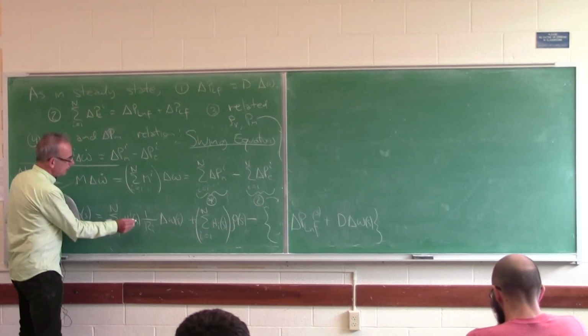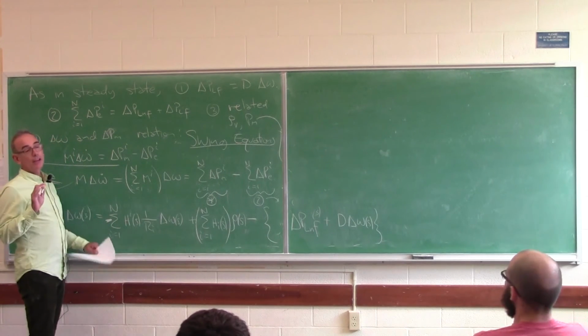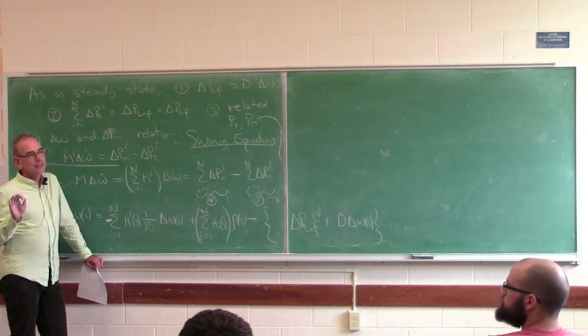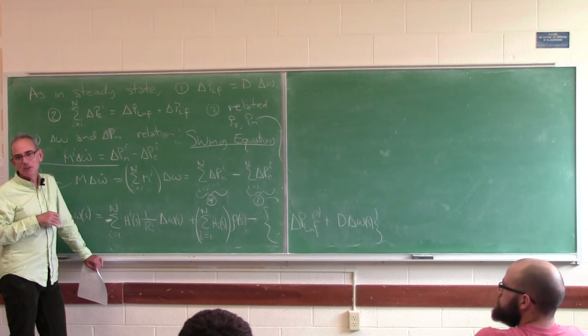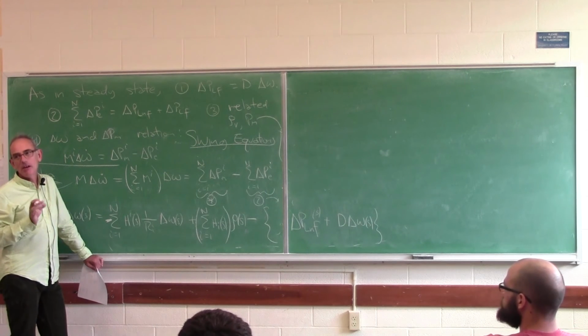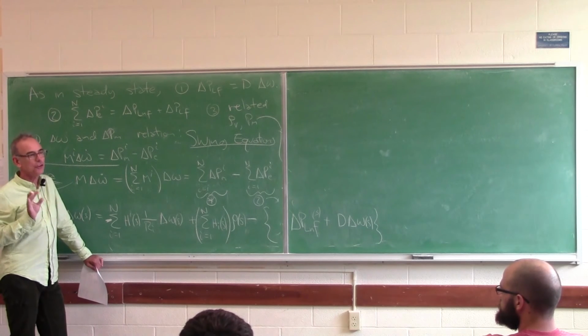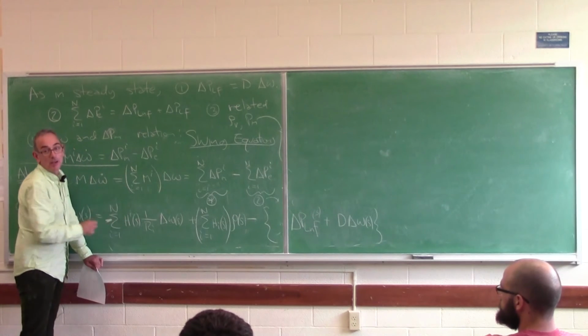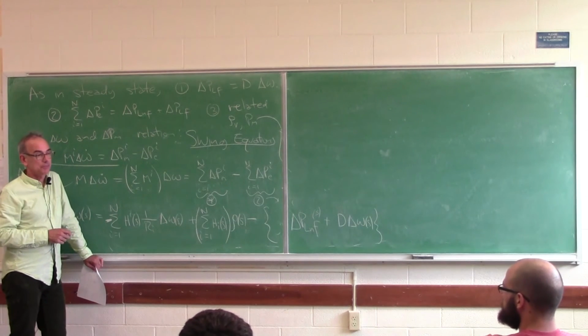All right. So each of these H_i was actually a second-order linear system. Let's pretend the valves don't matter very much, and pretend it's a first-order linear system. And by design, their pole locations are all similar, which is true. And so we could actually approximate the entire sum by a first-order linear system.